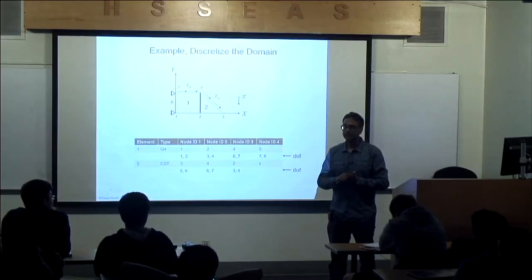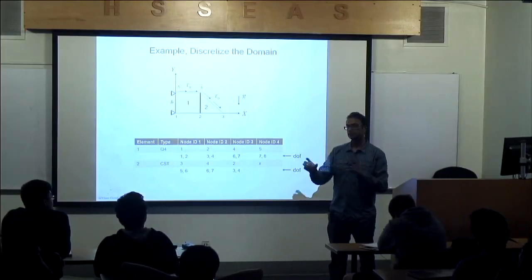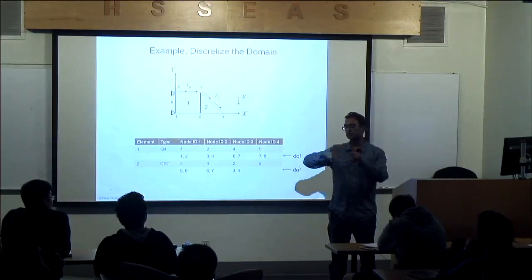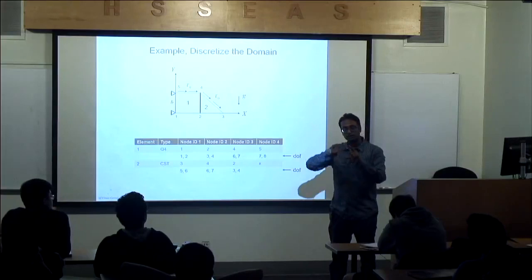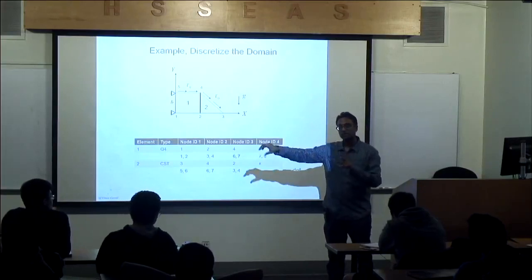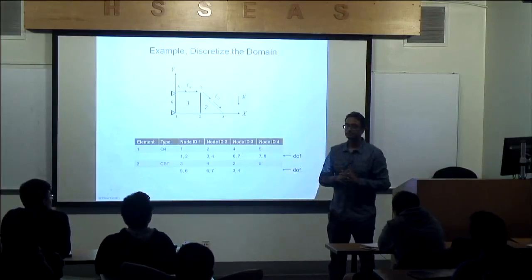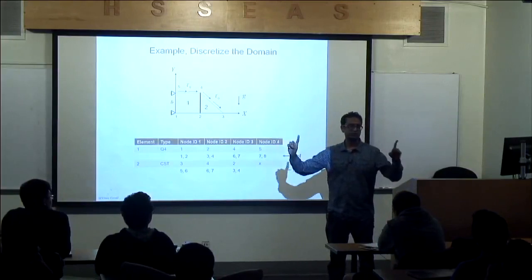The second problem, I think, is a bunch of triangles, isn't it? If you look at that problem, almost all those triangles have about the same shape. So when you calculate integrals, they're all going to be very similar to each other. If you number the elements correctly, and number the connectivity in a smart way, you can get it all to look the same, except for two triangles in each of the edges.